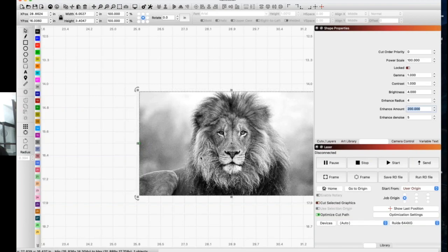Just keep your DPI low and increase it as you go on. Keep your speeds low and minimal power. You just want to create little pinpricks, is basically what you're trying to do. Sure, you're tattooing with a light beam. There you go. I saw that video too.